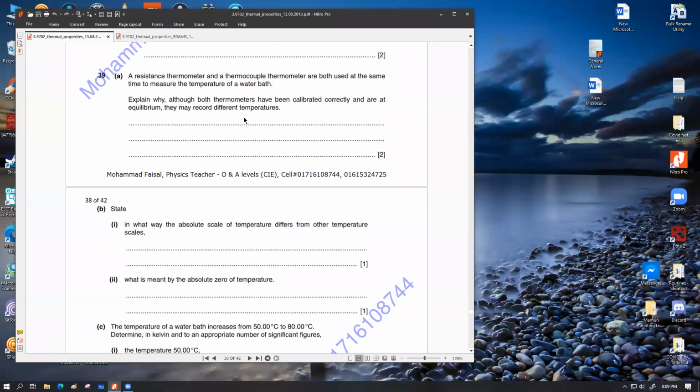It is not necessarily true that the curve we get out of some sample temperature values in the calibration process is exactly accurate for the actual values of the individual graphs. Let's say for a resistance thermometer you took calibration values for every 10-degree variation, got some points, made a best fit curve, and used the curve as the governing equation for how temperature will be calculated on the digital scale.